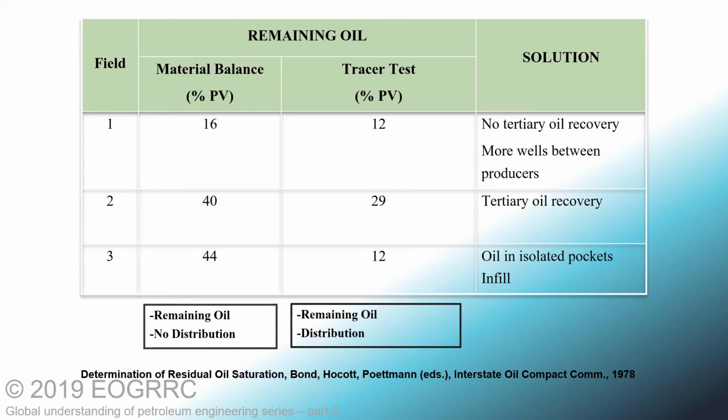As can be seen in the previous examples, a reliable in-situ measurement of SOR can define the target for enhanced oil recovery, or EOR, and also allow estimation of the potential bypassed oil in the field. This movable oil is the target for infill drilling and/or tertiary oil recovery. Since there is not an absolutely reliable model for predicting SOR, different SOR measurement methods can be used to evaluate a reservoir field. Based on the reservoir evaluation results, appropriate mature field development technologies can be considered.